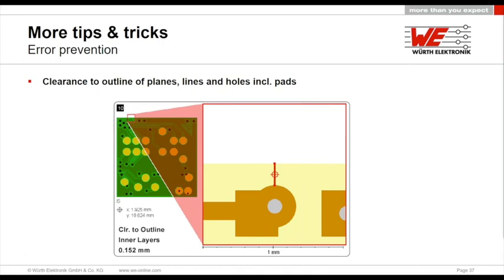Please have a look into your layout. The more effort you place in your rules and your layout, even if it takes a little bit more cost in your house, it still might save you a lot of cost when it comes to series production, because each PCB could cost less, so that the increased cost in your house easily can be matched by the decreased cost in our manufacturing.